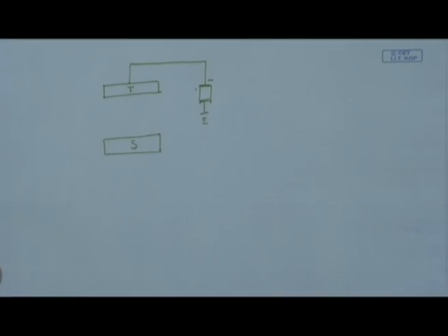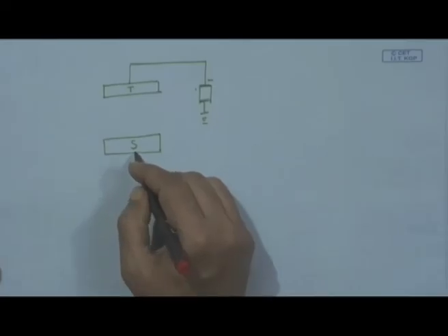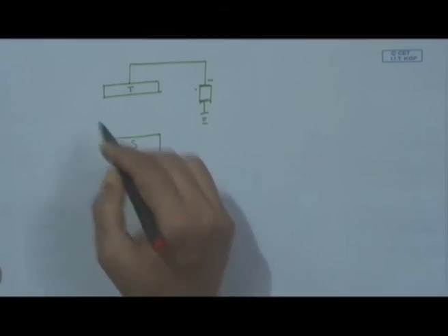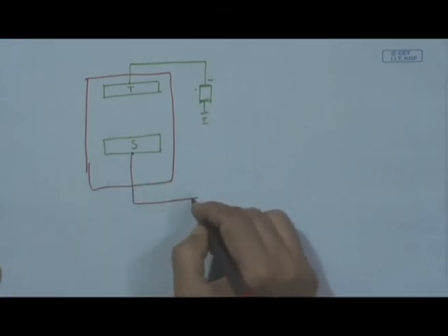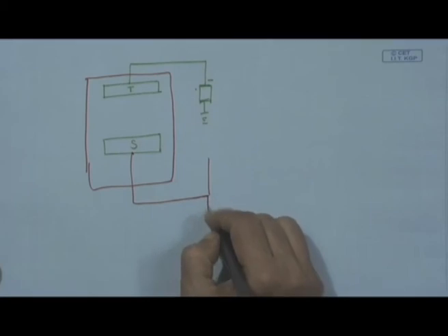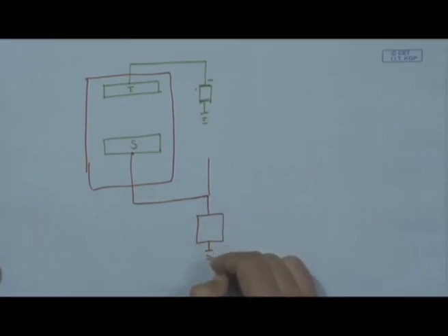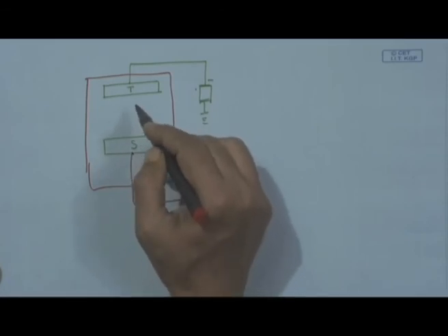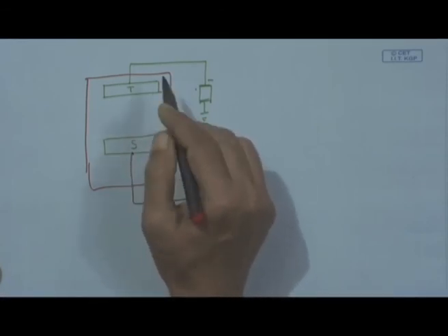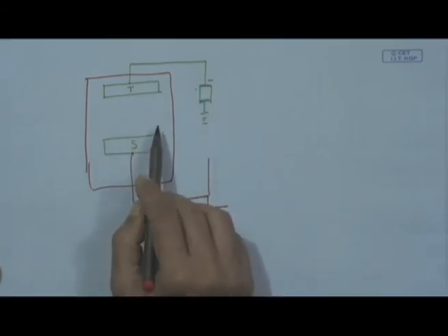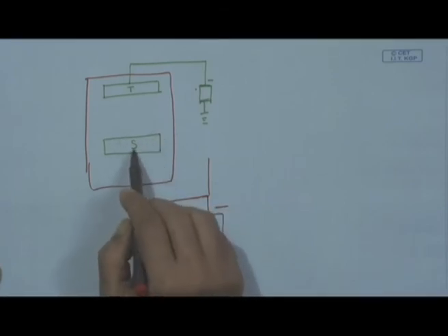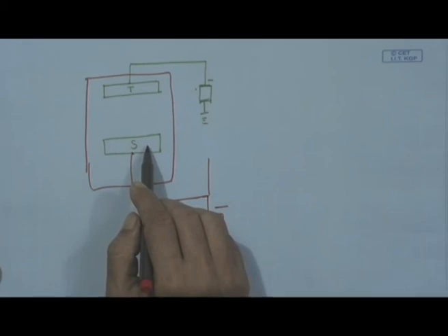So it should be the substrate, and here one can look into this substrate, and here we can have some kind of biasing. With this we can have substrate biasing, that means it can be during sputtering, it can be before sputtering, and that can be used for cleaning the substrate and also changing the structure of the substrate during sputtering.